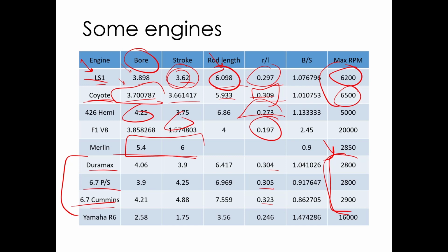When you squirt the diesel fuel into the cylinder and it burns on the boundary of the droplets in the air, it just takes time for those droplets to burn. Even with those really high, almost 30 to 40,000 psi systems, there's still a limit for how quickly you can burn the fuel. Now these engines will usually be mechanically able to rev quite a bit higher than this.